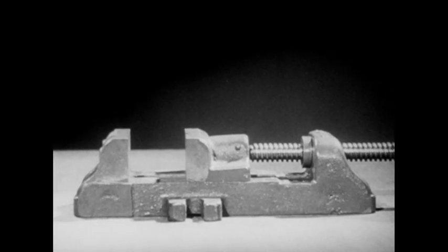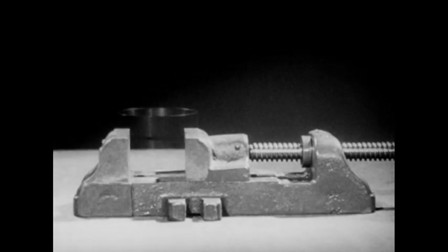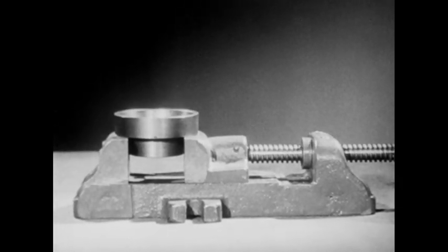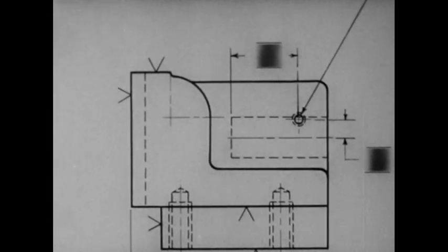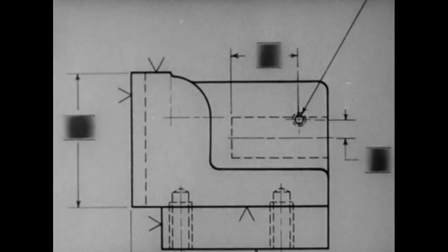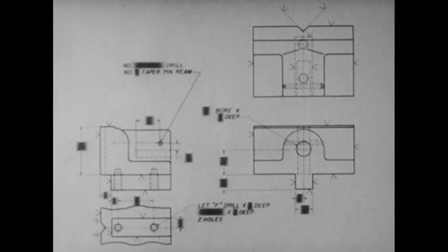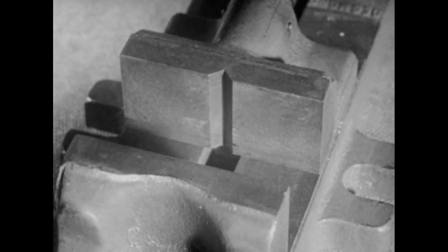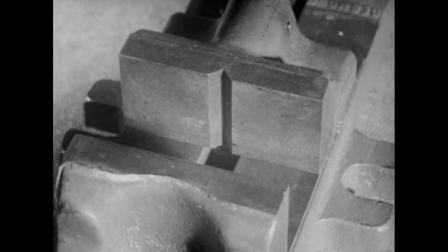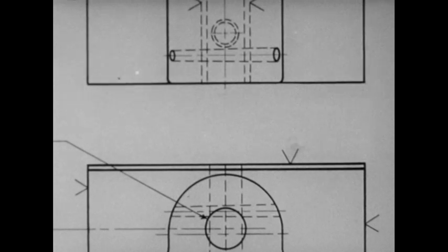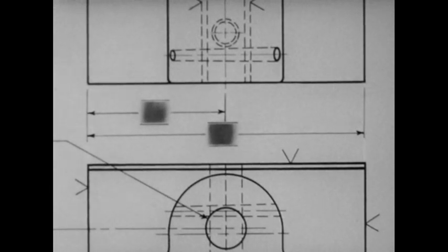The height of the movable jaw must be the same as the height of the base jaw to assure alignment of parts which are held in the jaws and rest against the top surfaces. Show the height of the movable jaw on the side view. The width of the movable jaw must be established to correlate with the width of the base jaw. Give the width dimension and, to control symmetry, give the half width also.